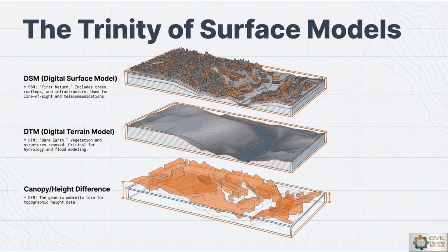The digital elevation model is the digital equivalent of a topographic map, but more powerful as it allows for automated calculations of volumes and drainage patterns. So we distinguish the digital elevation model from a digital surface model, which includes buildings and trees. As civil engineers, we usually prioritize the bare earth, that is digital elevation model, for study purposes.